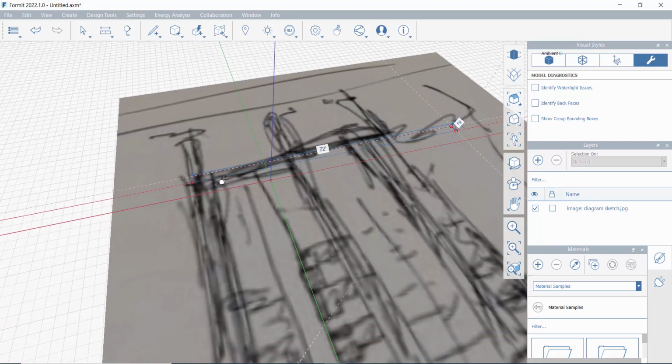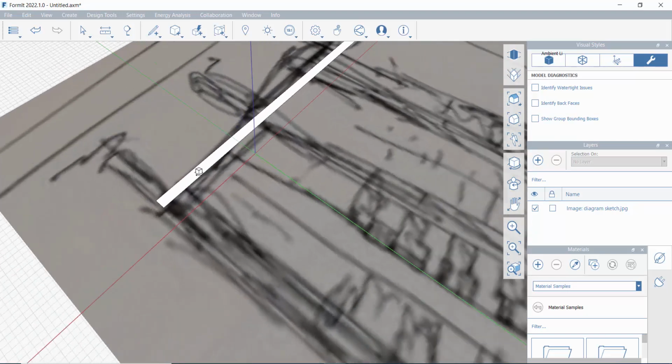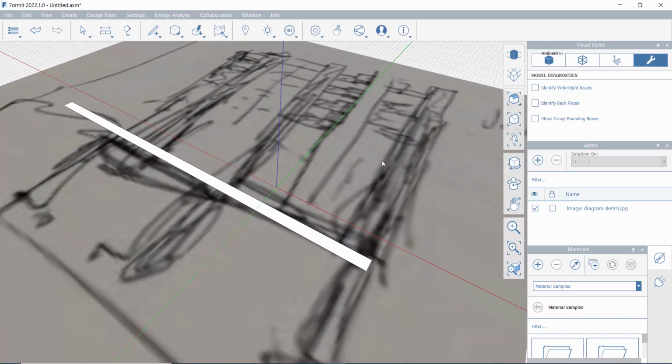And then I'm going to come all the way back down. So again, I'm on the red axis again. And I'm looking for the end of that line. The end of that line is right there. And as I drag that line, I want you to kind of watch what happens. Again, it's going to find the inference for the other line. Because it knows, Betty's making a rectangle. Not positive, but Betty's making a rectangle. So it's going to find that inference for you. So I can left click there. I can click back to my beginning point, and I've made a solid polygon.